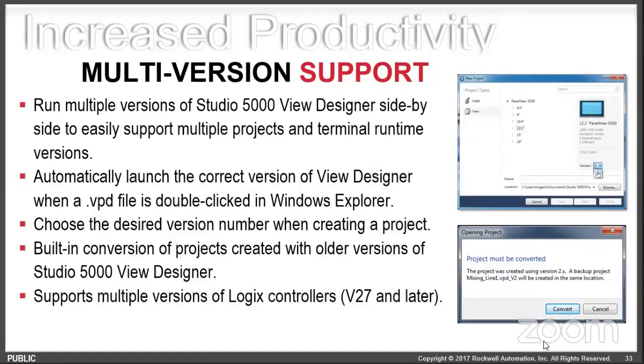So for anybody that's opened up or installed Studio 5000 after version 27, it now gives you different options on what you want to open, whether it's Logix Designer, View Designer, which is what we've been talking about, Application Code Manager, or FactoryTalk View SE. What you'll see here is a very similar look and feel to how you program in Studio 5000. So now you can open it up and have multiple versions of the View Designer installed on your box.